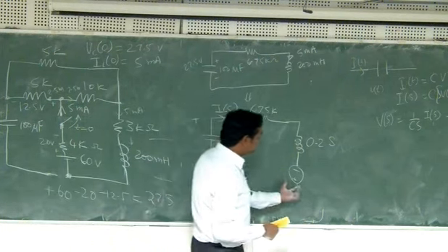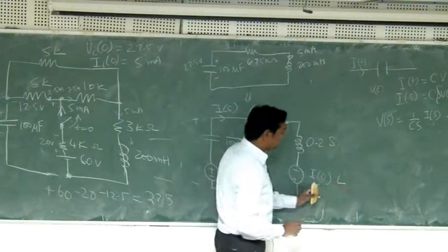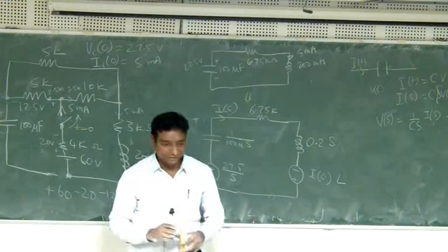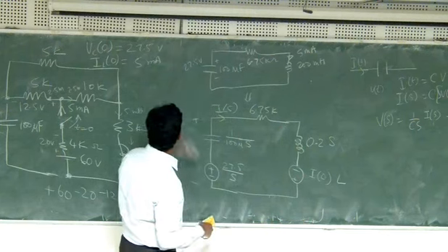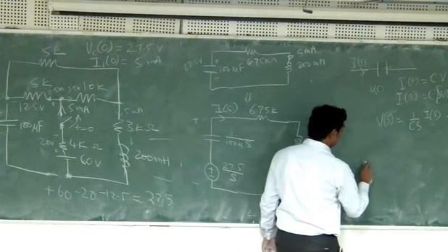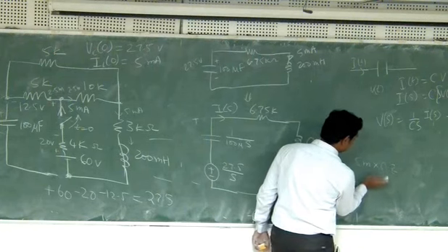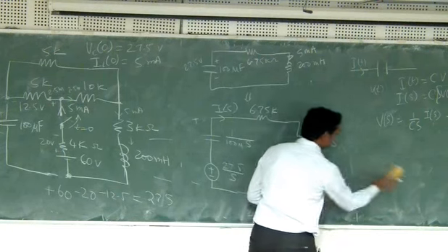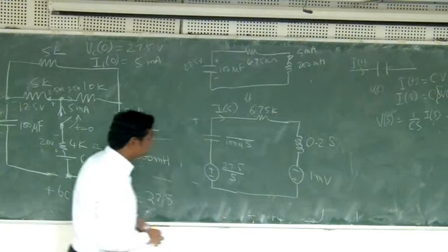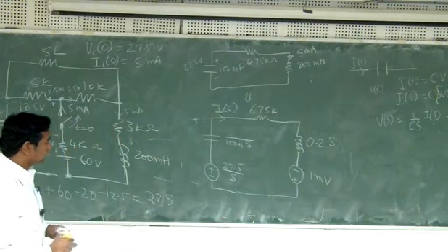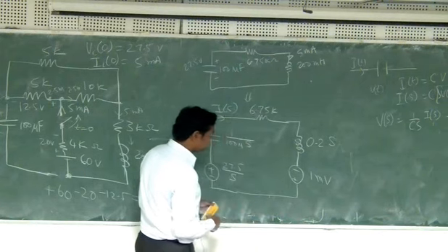That's another quick way of defining what way the voltage will be. And what will be this voltage? This will be, is it like this? I0 into L. Remember there was one term L into I0. Okay. So L was 0.2 and I0 is 5 milli. So 5 milli into 0.2 is 1 millivolt. Almost negligible, but anyway, 1 millivolt. But it will be in the downwards direction. Will it have by S also? Into S?